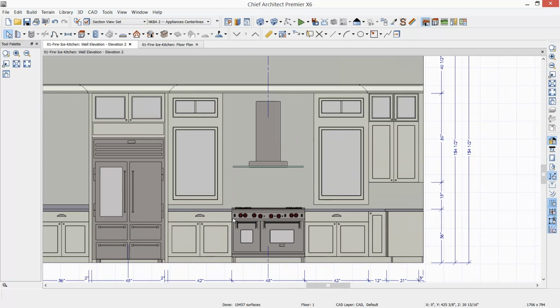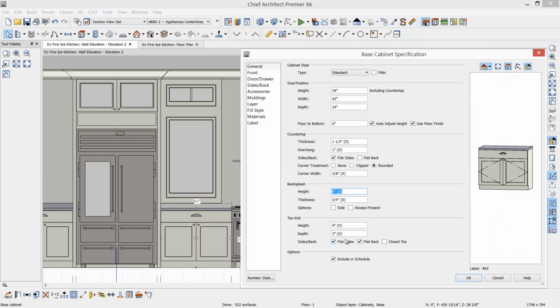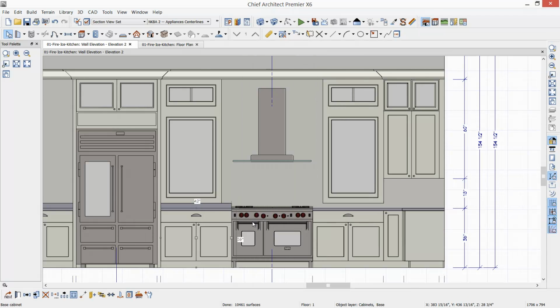The other cabinets, if I do the same thing to the cabinets on either side of the cook hood, that's going to leave a backsplash. Let's just go ahead and set that to be 3 inches. It's going to leave a backsplash that overlaps in this area, and then I've got to create my backsplash that might come in and jag around that behind the cook hood.